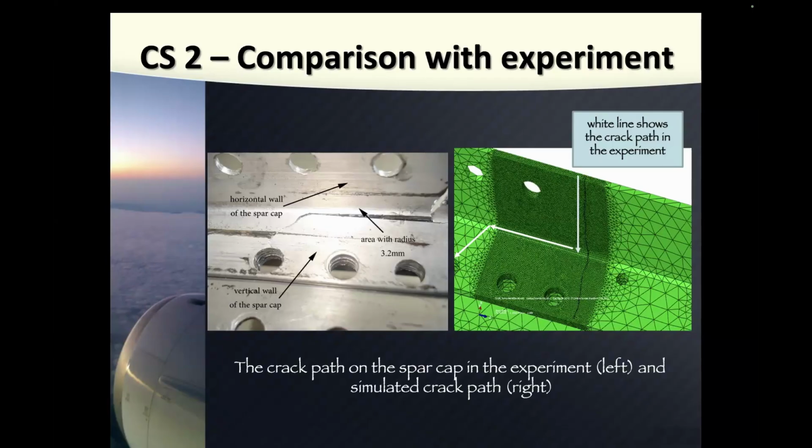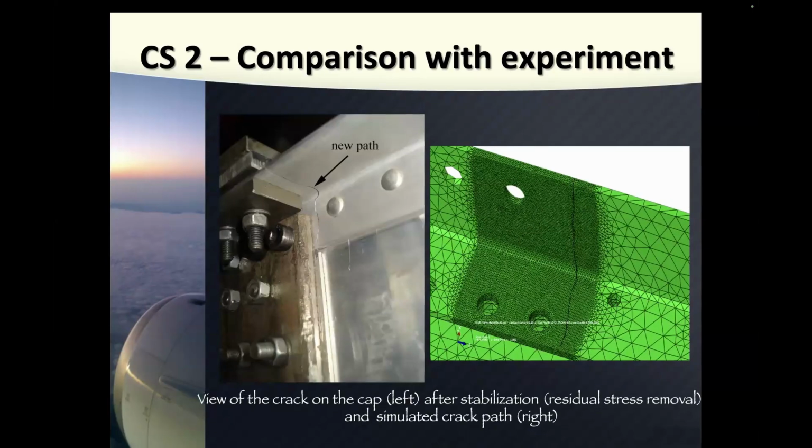And it's very important after that to use stress relief methods, because you have some residual stresses after that. So my conclusion was that maybe there is some residual stress here. So we ordered and paid for a new spar in which all parts went through heat treatment, and what we got, the new spar, looks like this.